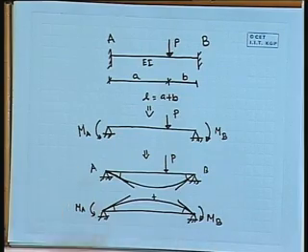So two unknowns at two places we have to look after the deformation of the structure, right. Now intentionally I have put the load in a very arbitrary place, so the distance is A and it is B. In a special case, if I put P at the center of the beam, say at L by 2, in that case MA should be equal to MB. So we could calculate only one quantity, only matching with the slope at A or B.